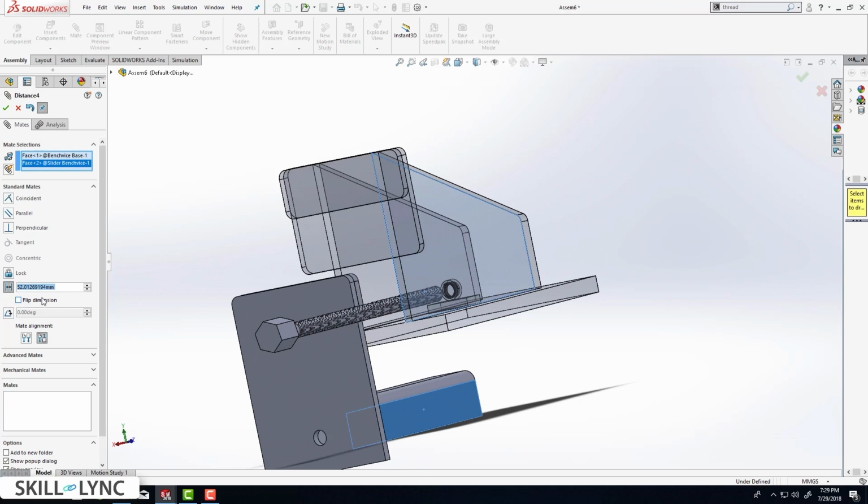This should not happen. So to fix this, we are going to give a coincident mate. So select this particular face, right? Let's select this face, and we're going to select this particular face. This way it's going to create a coincident mate, and click on OK. Hit escape, and now if you try to rotate this particular screw, just using your mouse pointer, the slider is going to move automatically, and you can check it in both directions, and you can see that we have assembled it perfectly.